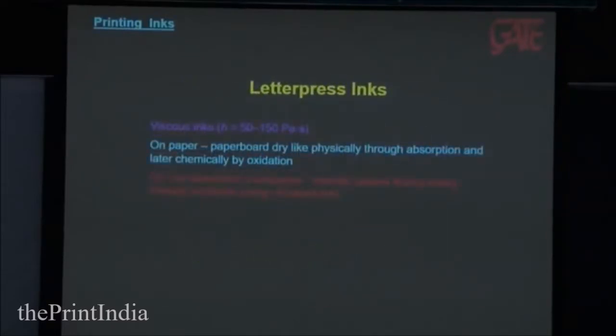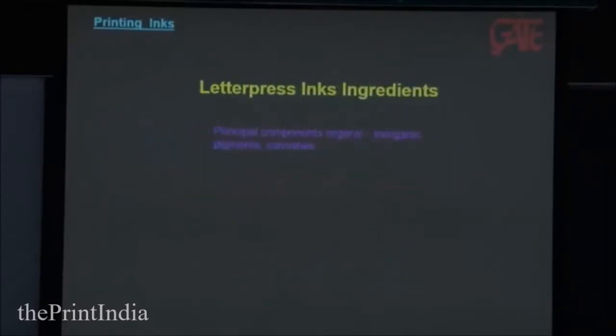Letterpress inks: viscosity goes very high, to 150 pascals. On paper and paperboard, they dry physically through absorption, later chemically by oxidation. On non-absorbent, transparent and metallic papers, they dry slowly through oxidation using oil-based inks. Something like heat set. 1 minute.